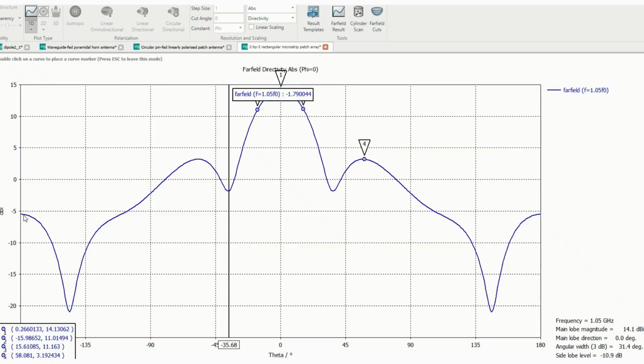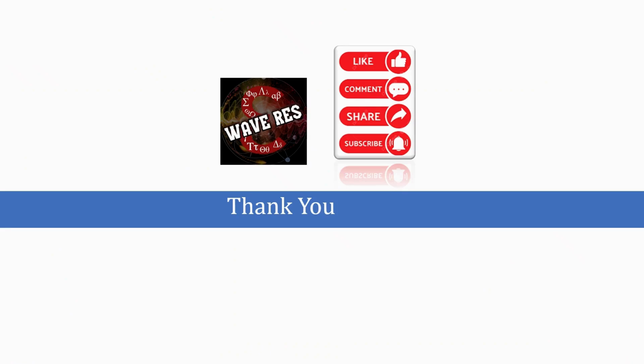So this is how the radiation pattern is defined. We saw that we are getting a lot of information like side lobe level, minor lobe levels, and back lobe levels from these radiation patterns. This information is very useful in deciding whether the designed antenna is useful for a specific application or not, because these side lobe levels may cause a lot of interference to the main lobe due to reflections. So the radiation pattern forms an important parameter in designing antennas.